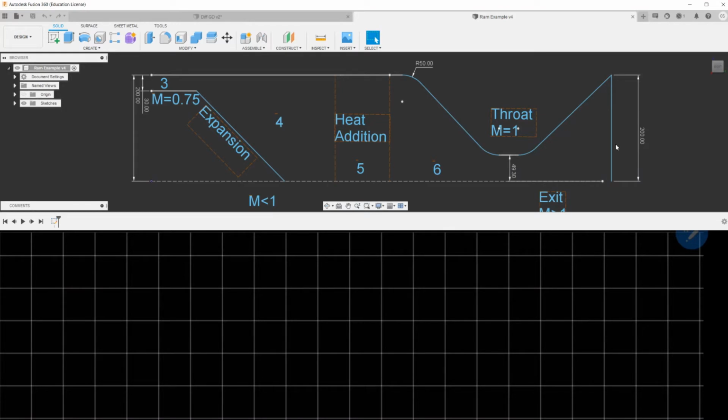And one aspect that you just asked about, constraining the inlet of the combustion chamber or exit of the diffuser: you can do it, but physically you can constrain only until you reach Mach 1 in this section.